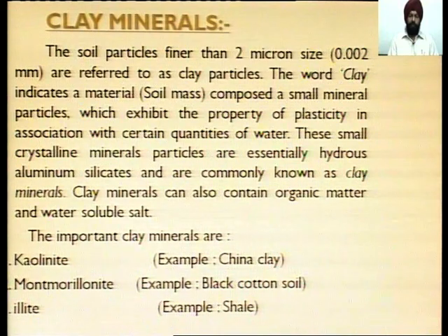The important clay minerals are kaolinite, for example China clay, montmorillonite, as in black cotton soil, and illite, for example shale type soil. So, these are the three important clay minerals: kaolinite, montmorillonite, illite, present in the clay particles of the soils, which provide the plasticity to the soil when associated with a certain amount of water.